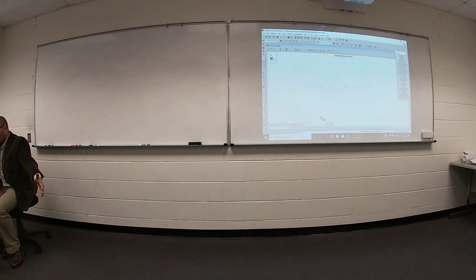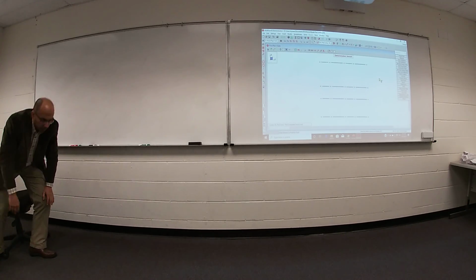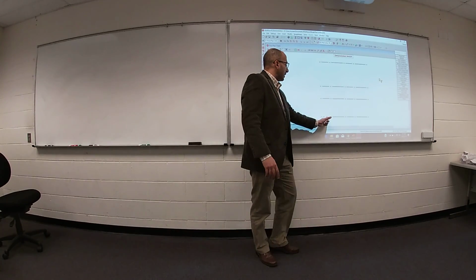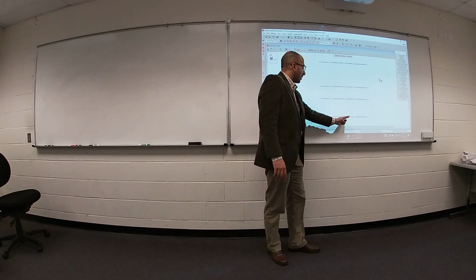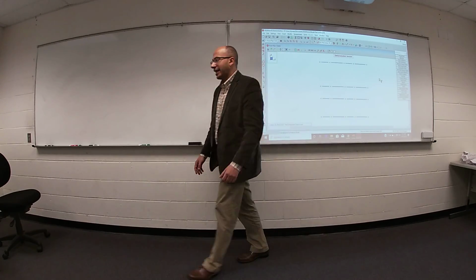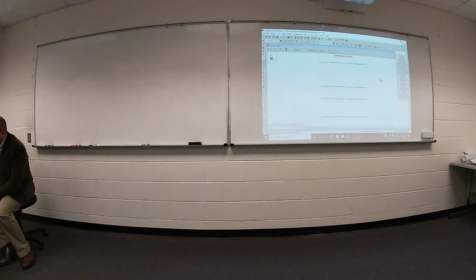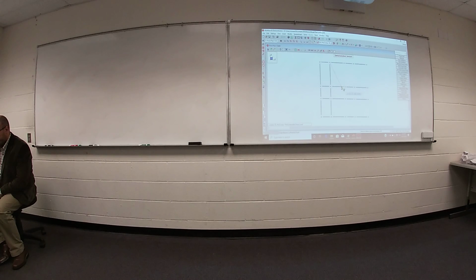If you remember, I would like to draw from left to right, from left to right, each horizontal beam. So now I can say, the start point for each beam is from this side. For this beam, here is the start, here is the end. For this beam, here is the start, here is the end. For this beam, here is the start and the end. For any vertical beam in Y direction, from down to up, like this. Once you are done, escape.